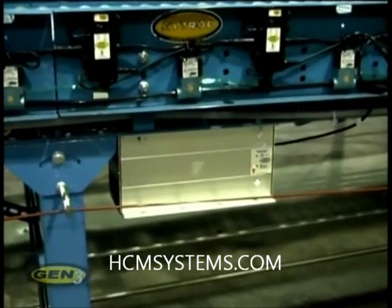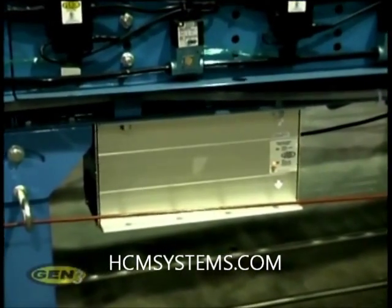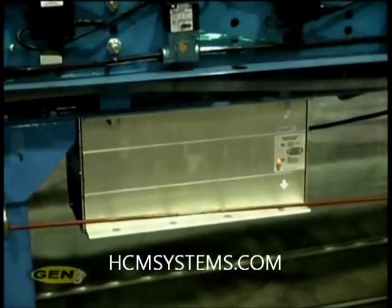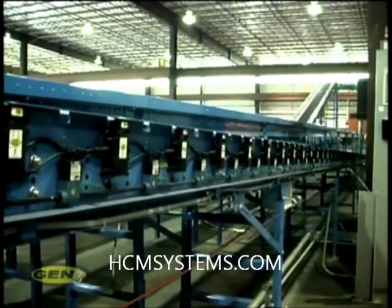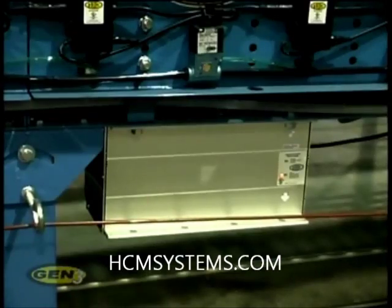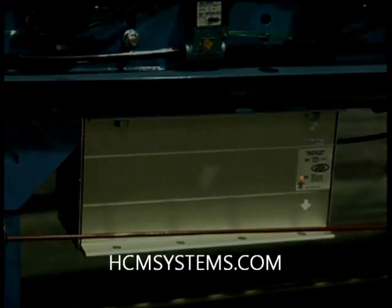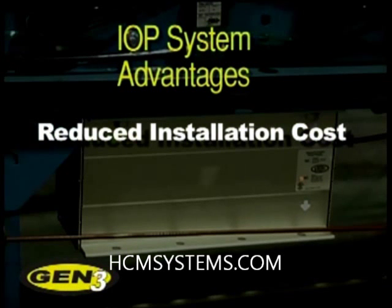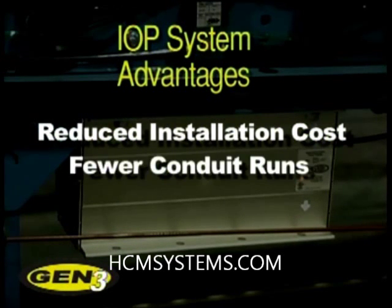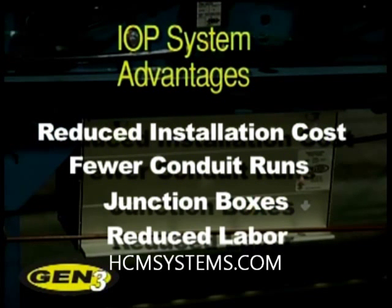With the IOP system, all control wiring to and from external control devices is connected to the centrally located IOP unit, which then distributes the inputs and outputs to the proper zone controllers of the conveyor. The IOP system offers several advantages to the integrator, installer, and end user. Some of these advantages include reduced installation cost, fewer conduit runs, junction boxes, and reduced labor, all help to reduce upfront costs.